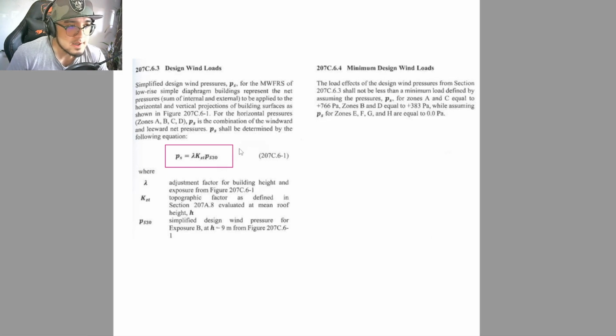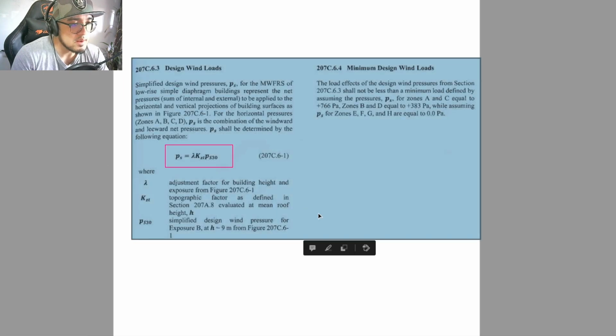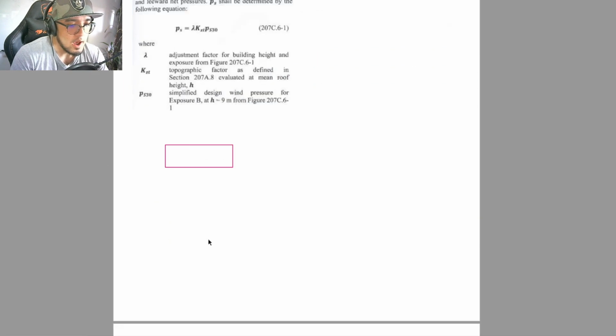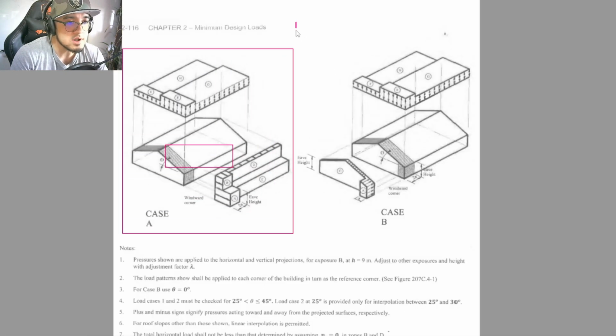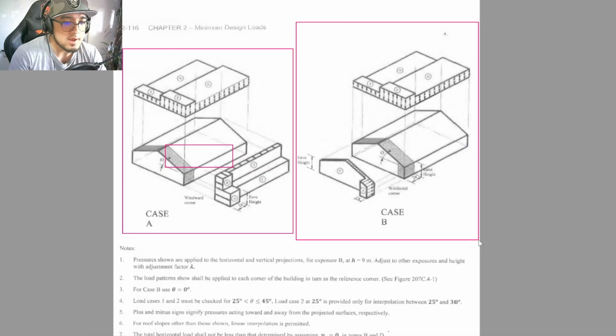Unlike in our seismic load definitions in the previous video, wherein we just indicated the parameters in STAAD and STAAD generated the base shear, in this method we will solve for it manually, and then apply it manually once again. Disclaimer, everyone: in this video, I will only solve for case A right here. As for case B, you can do it as your own practice problem.